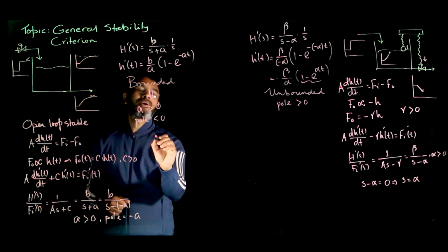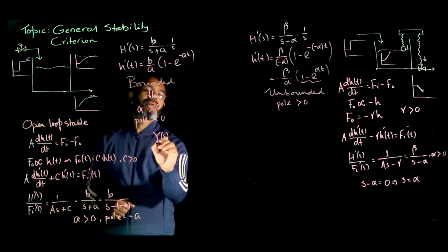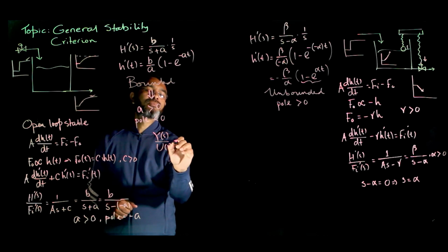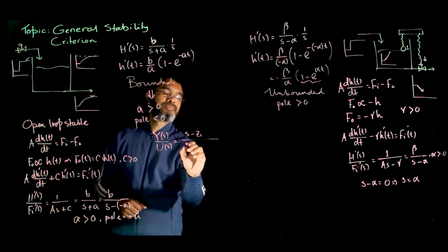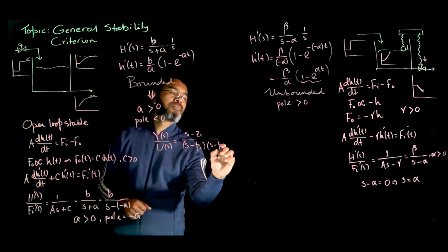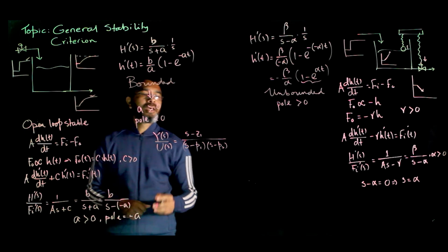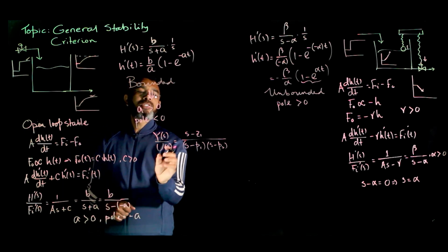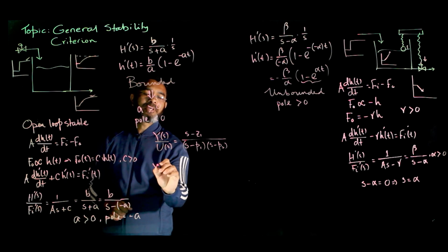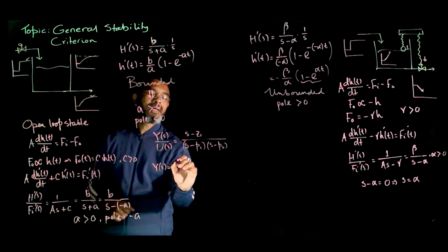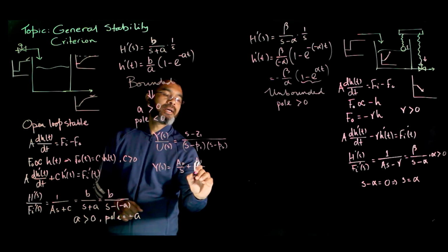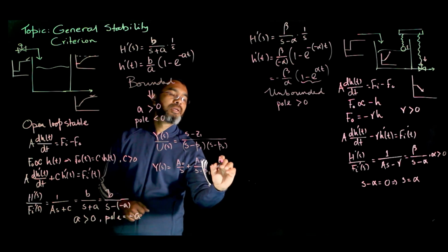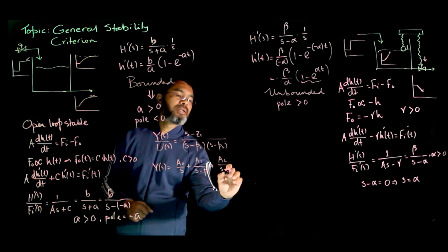Now the same thing you can see for a general transfer function. If we have Y(s) over U(s), say, if we write it in the pole-zero formulation, the step response due to a step change in U(s) can be expressed as Y(s) will be, suppose, a naught over s plus some constant a1 over s minus p1, plus another constant a2 over s minus p2.